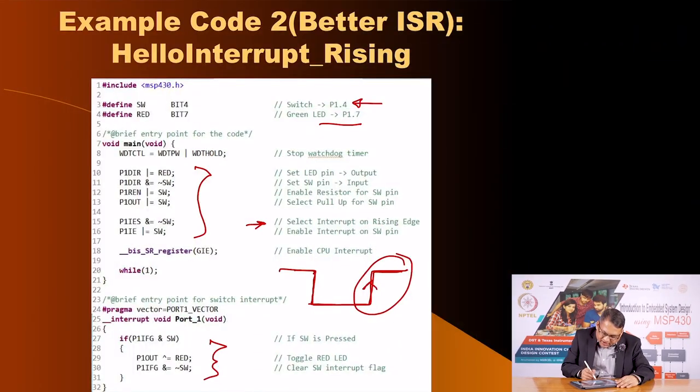So, the interrupt subroutine here is a very simple piece of code which just toggles the LED. No delay instructions are included in the interrupt subroutine, and this instruction will reset that interrupt flag, so that next time the switch is pressed it will be entertained.